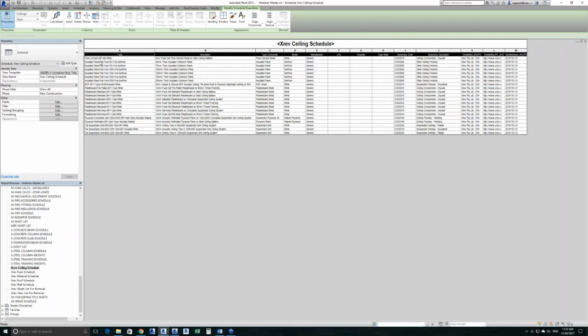So we have fibre cement, insulated panels for various thicknesses, MDF, plasterboard, different types of plasterboard, whether it be fire rated, standard or wet area, concealed grid plywood ceilings, perforated plywood, suspended grids in different sizes, some acoustic, some not.